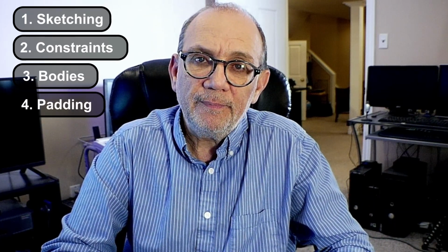These are the concepts that I'm going to cover in this video. Number 1, creating a sketch in FreeCAD. Number 2, applying constraints to your sketch. Number 3, creating multiple bodies in the same project. Number 4, padding or extruding your sketches. Number 5, exporting your model as an STL.